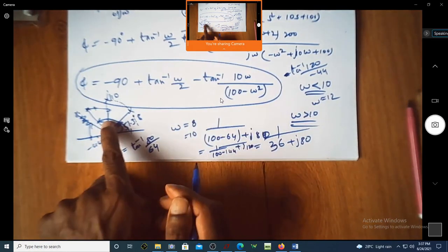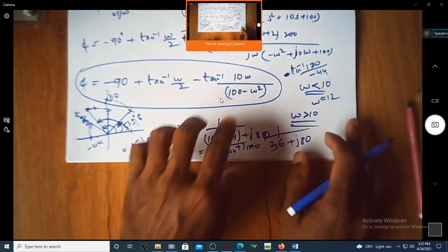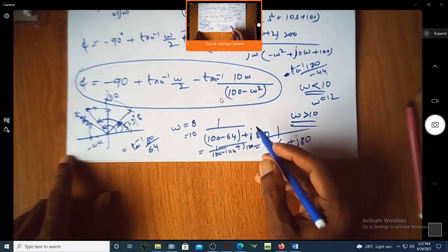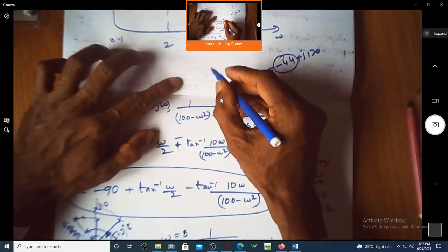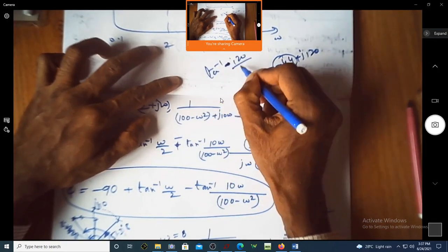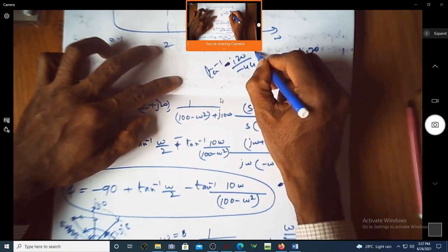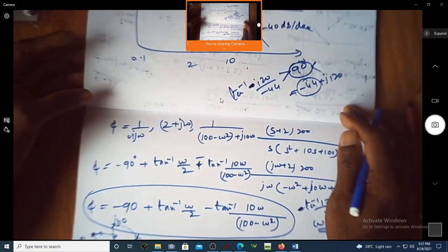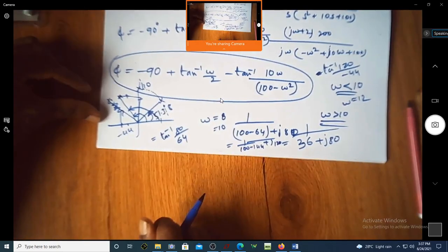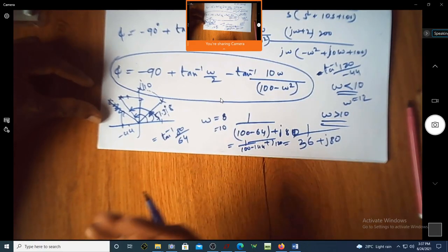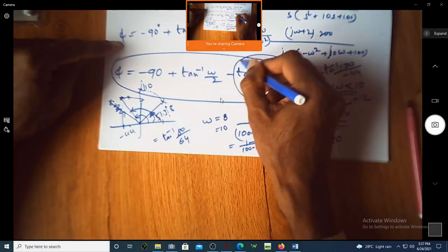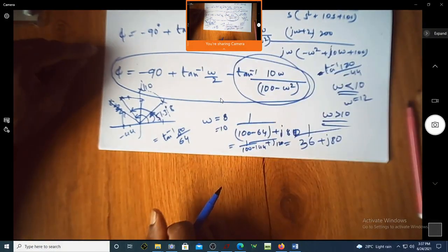Since I'm supposed to find this angle, when I actually do it using this, tan inverse of minus, sorry, 120 divided by minus 44 is not giving me more than 90 degrees. But actually, I should get more than 90 degrees. It has to be. What to do now? I need to make a correction to this phase angle. Only this part.